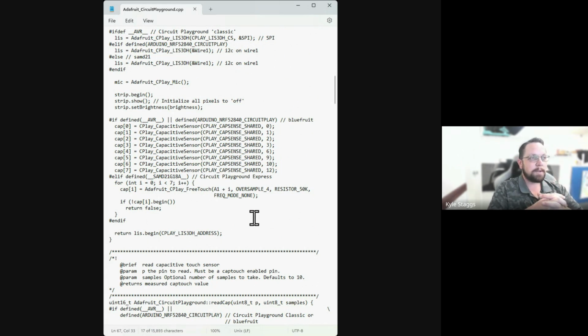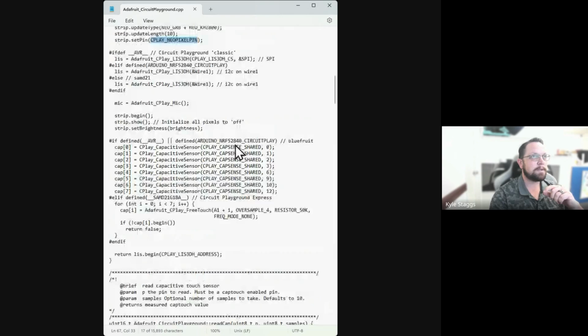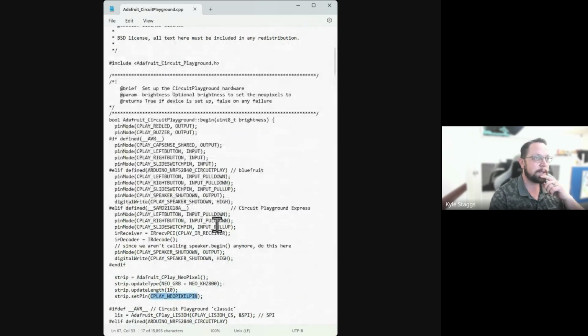So the difference between something like a pull up and a pull down resistor, to close this now open loophole because curious minds want to know. Pull down resistor means it's a resistor meant to pull the voltage on that part of a circuit down to 0 or ground. Pull up resistor means it's trying to pull it up to whatever the nominal voltage is. 5 volts, 12 volts. A lot of stuff on these Arduinos, depending on where it is on the board, is 3.3 volts. Give or take.